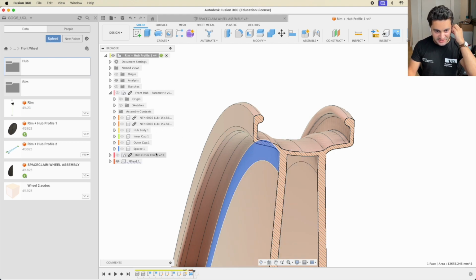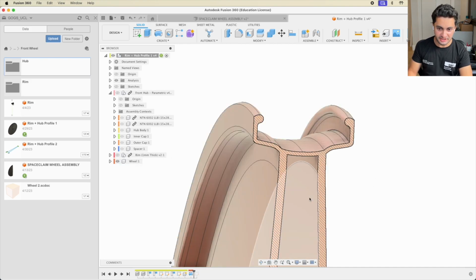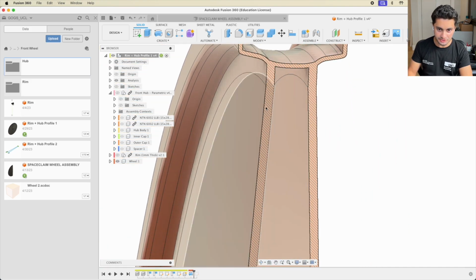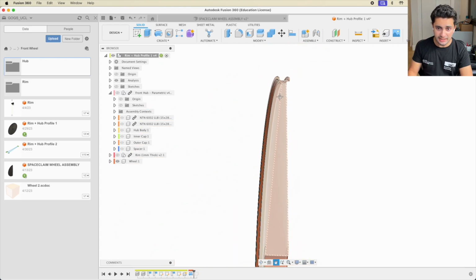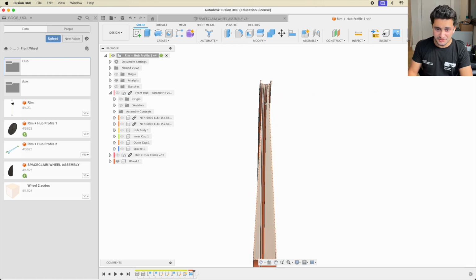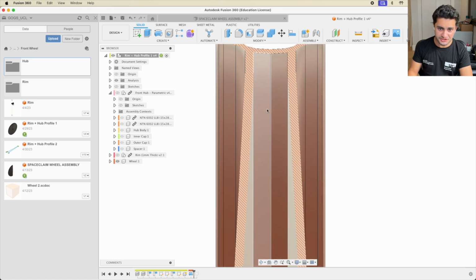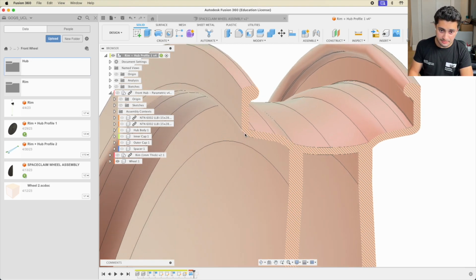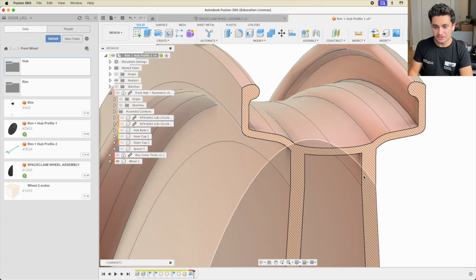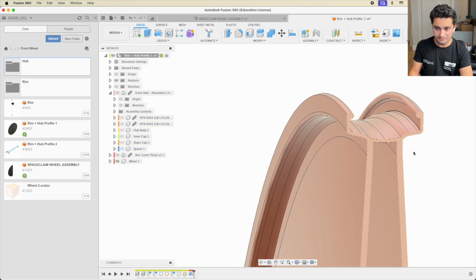Now, this wheel, you're probably thinking, does not reflect that because it's got relatively thin walls, it's got a big hole in it. These walls are at an angle as well. So if you're wanting to remove material, you want something occupying the most volume. In this case, that would be a wheel going pretty much straight down from the widest part of the rim and not really having a hole in it.